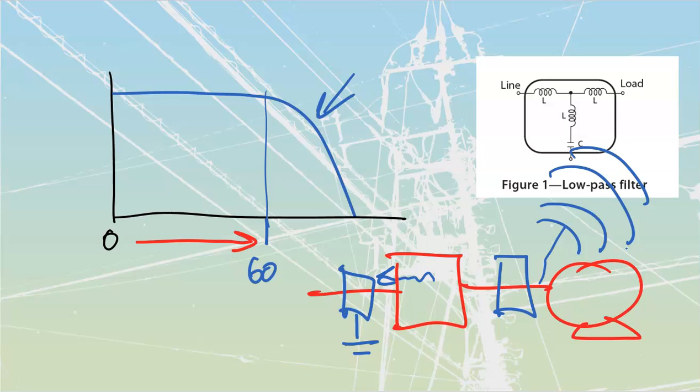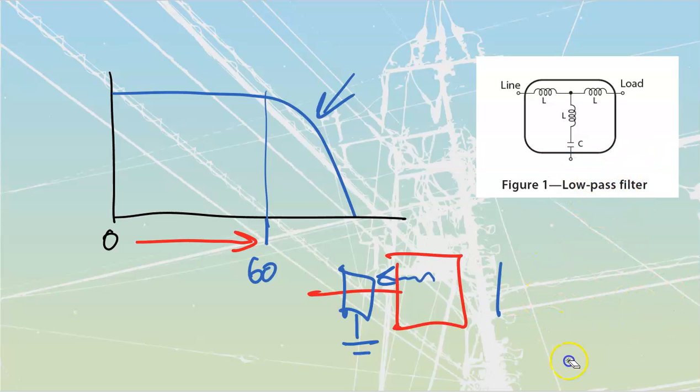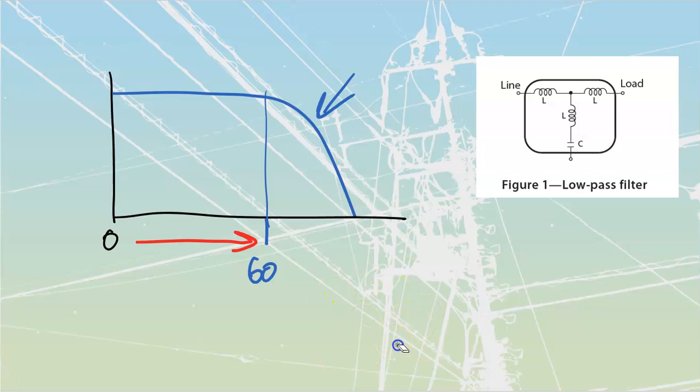Active harmonic filtering is a little bit different in that you've got CTs that are going to be placed on the system. And those CTs are going to be continuously monitoring and then switching in and out, either through saturable reactors, which are going to change XL, etc., or through variable inductance or capacitance methodologies that we have. You're going to be able to cancel out harmonics just by electronically running that in.